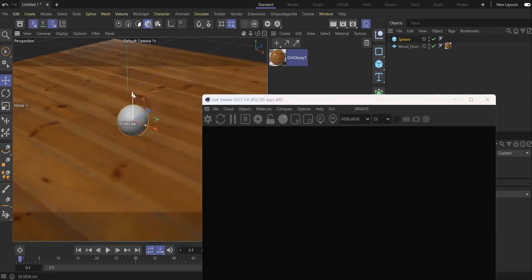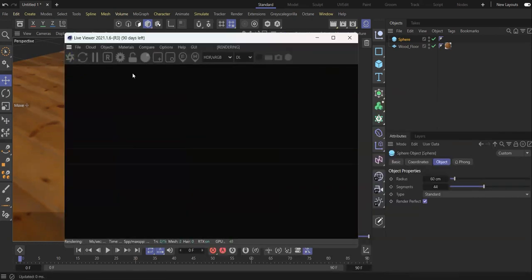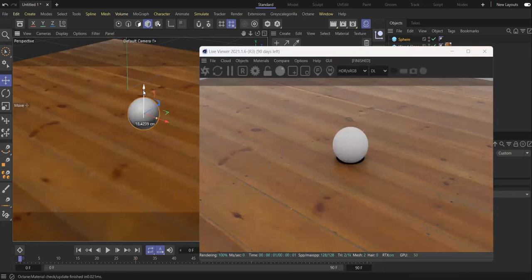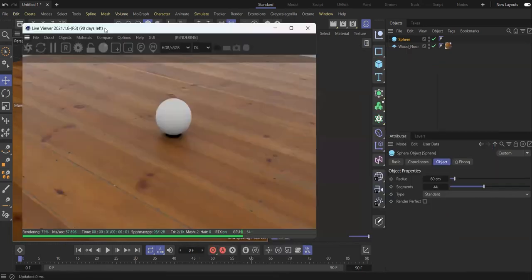And as far as placement right now, I'm not going to get too particular on that because I am going to be able to see what the displacement is moving on that surface. All right, I will just click render here. Now we don't have any lighting currently set up, but we can go to Polyhaven for that too. Because if you remember, on Polyhaven, we also have access to all the additional HDRIs that are on their site.